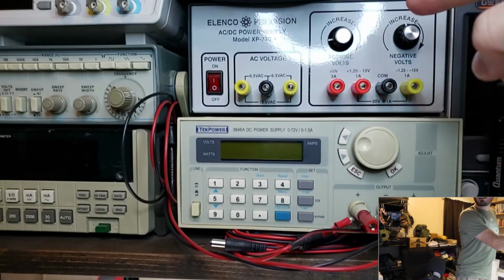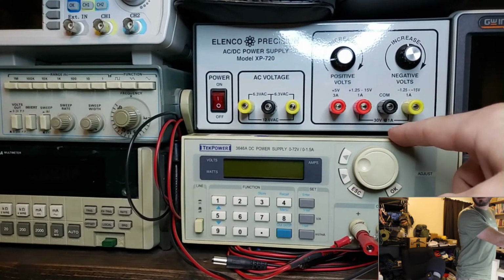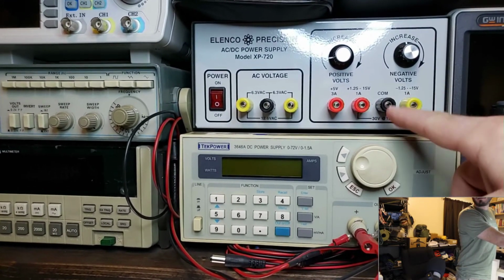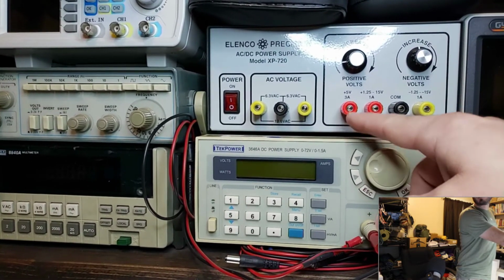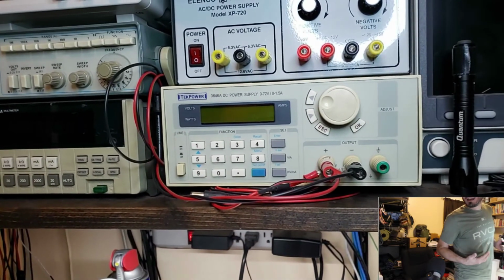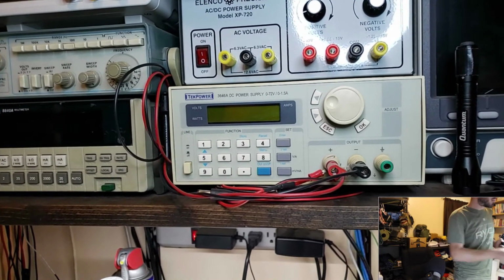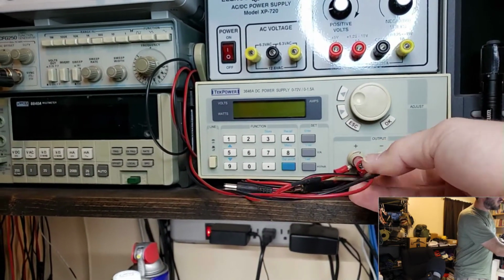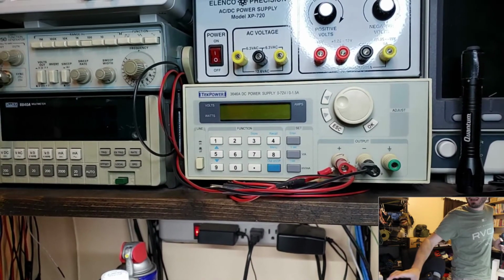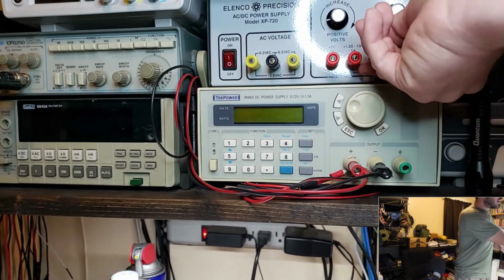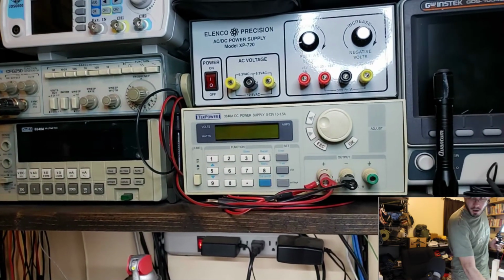I also have a second power supply above this with a few different features on this one, but it has the same thing. A black one for our negative terminal, and then for our positive voltage, we have this red one over here. That's generally the convention that we use, is black for negative, red for positive. And if you don't have banana plugs, because they do cost a little extra money, then what you can always do is, if you unscrew these, you can stick a wire in there.